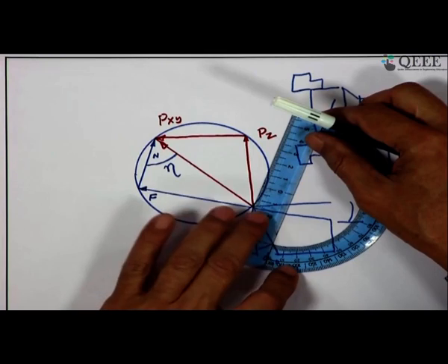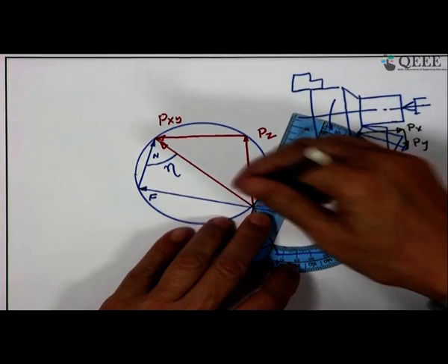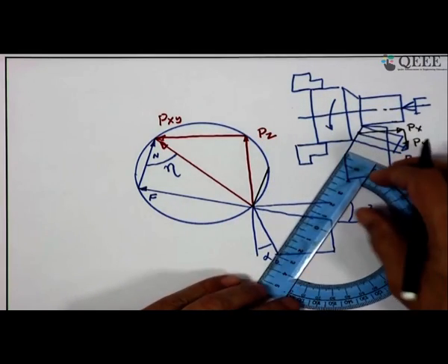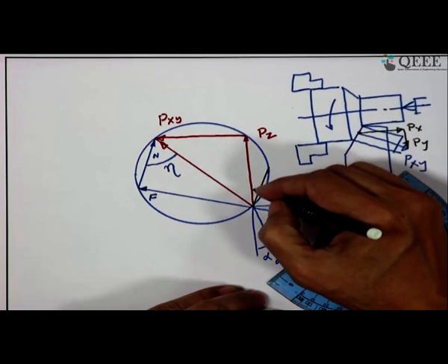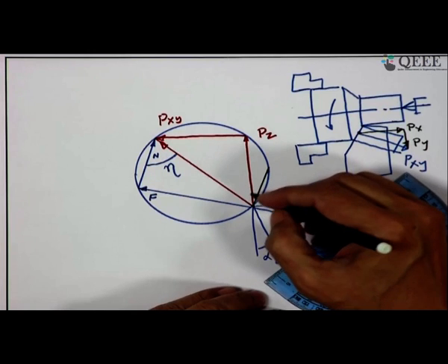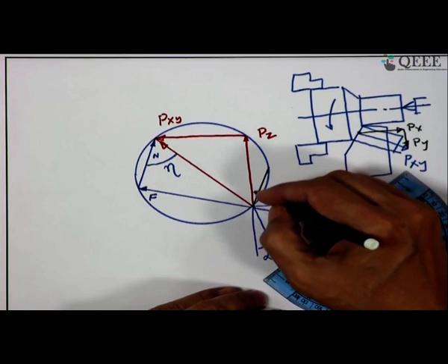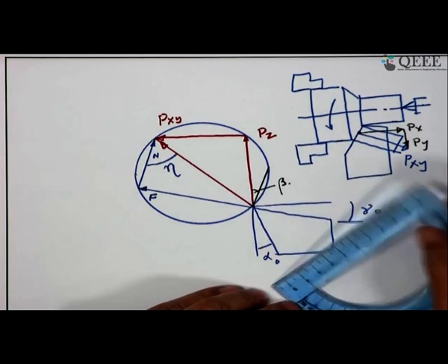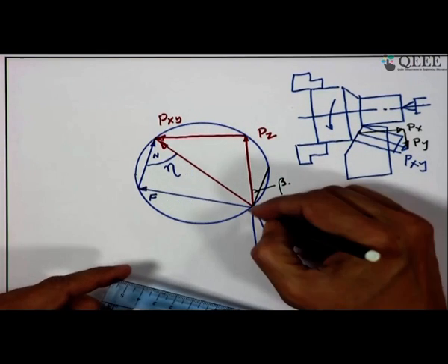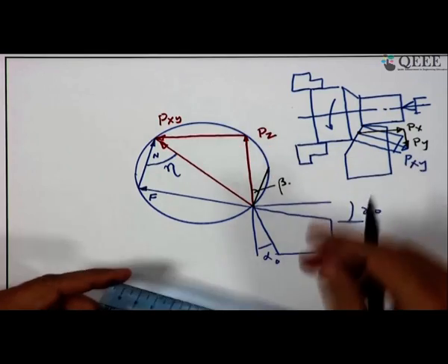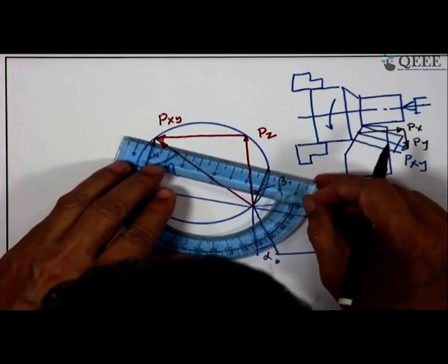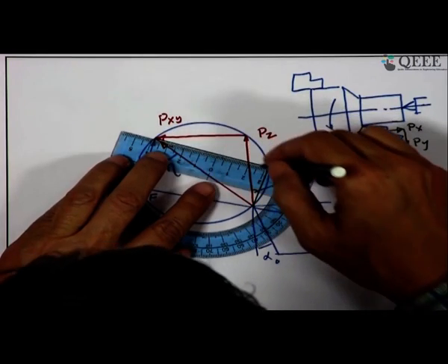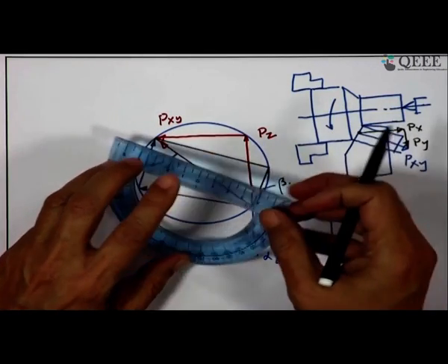Say this is your shear plane orientation. I draw with this. So, this is your shear plane orientation, and shear plane orientation means it is with the direction of velocity. So, this angle becomes beta, and what remains to be done, this is another intercept, and then I join this one.